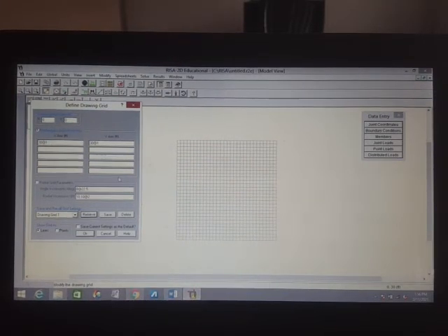So we can actually specify a grid that looks rectangular, or non-uniform, or square. So we can set it up like that. For example, the first one here says 30 at 1, meaning 30 spaces at 1 foot, and this one is 30 at 1 foot along the y direction. For the x-axis, we'll try, let's say, 2 at 20, for example.